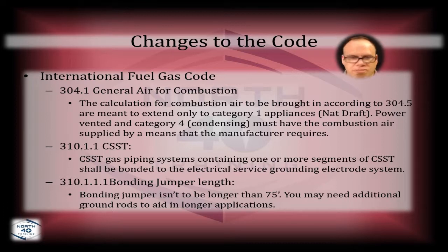And there are guys that immediately jump on that and say, no, you cannot do that because now that ground is an isolated ground. No, it's not. It still is going down to the grounding electrode system. So it still is going back and connecting to the grounded system. So it isn't isolated at all, but, you know, where there's a will, there's a way, right?